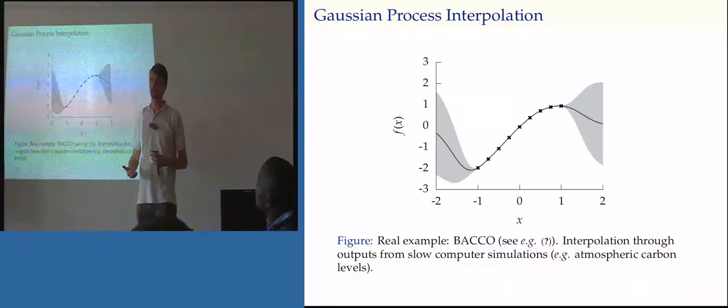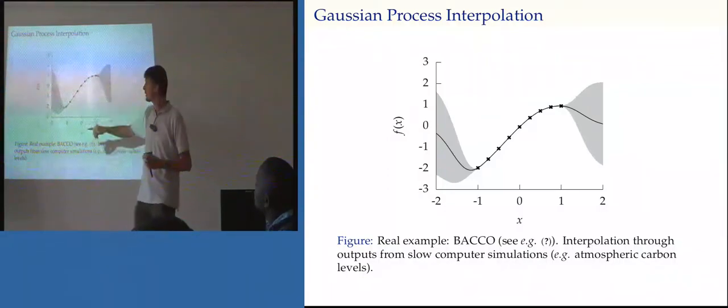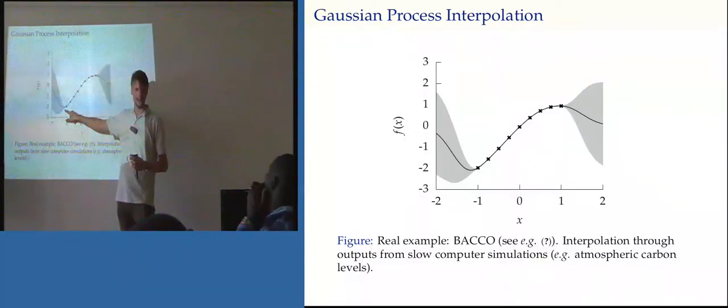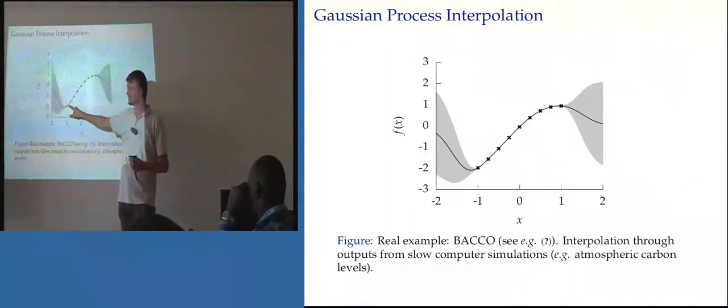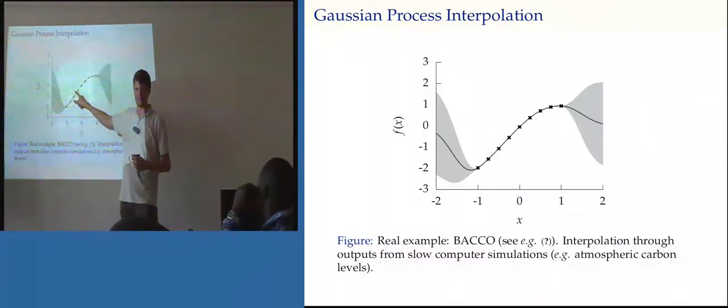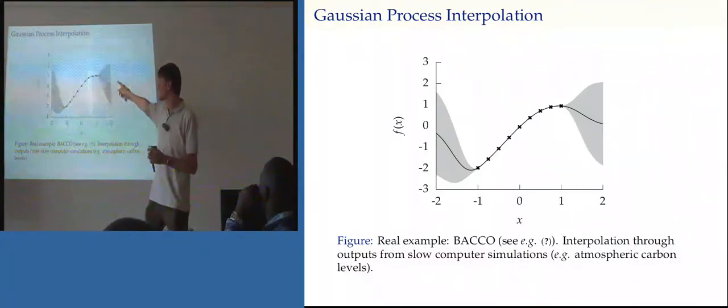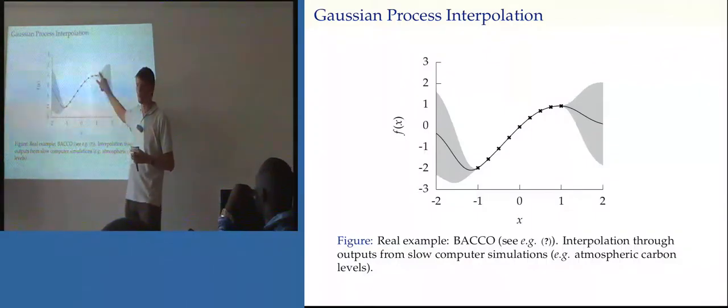And reconstruction theorems are based around the fact that if you know frequencies don't exist above a certain point, you can reconstruct your signal exactly. So they turn out to be rather odd, degenerate Gaussian processes. They collapse to 100% confidence. This one appears like it's done the same thing when we've got the sample rate down to a certain amount. Actually, there's a little bit of uncertainty, very small, between these things, but it's so small that you can't see it. And when you get into these types of domain, you can get numerical problems.